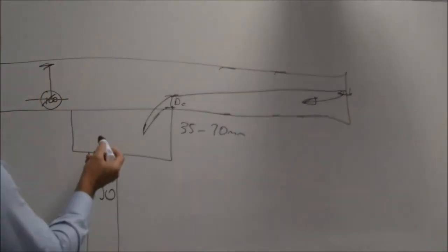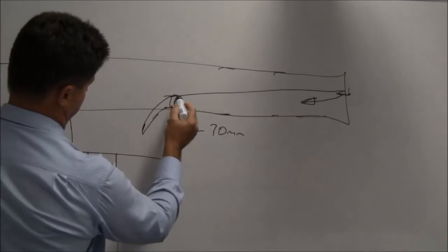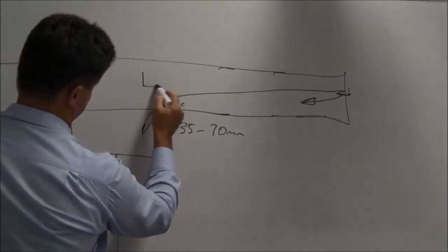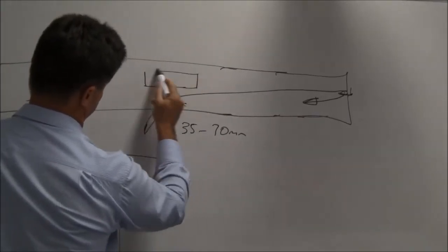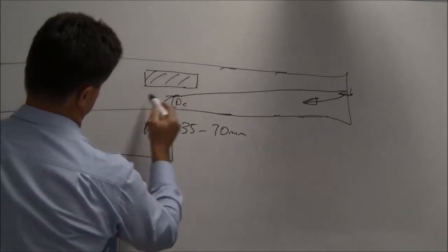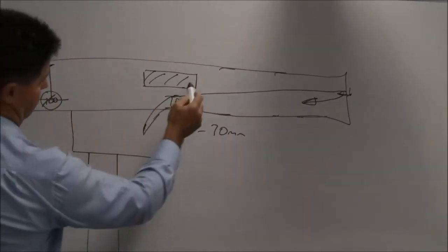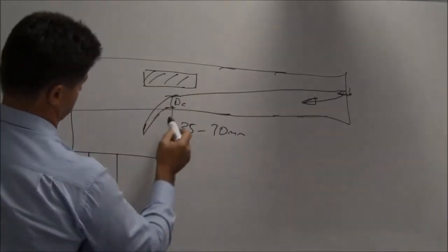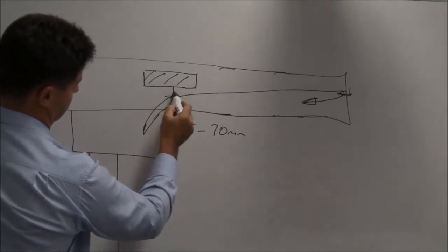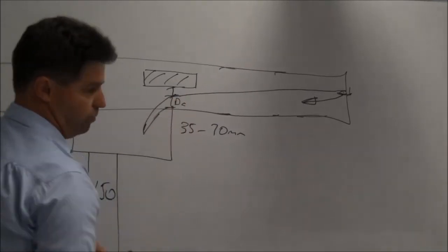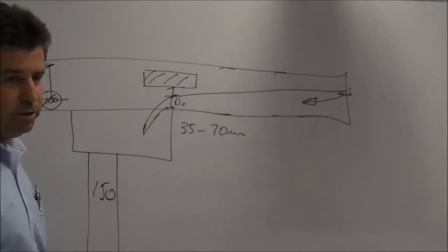So, all I'm saying in here, with the overflow itself, in our office we normally do rectangular, because obviously the surface area of that is a lot better than that. And we can just do a letterbox out the side. The reason for the 10 mil is because we don't want the overflow to work under normal conditions that we've designed to.